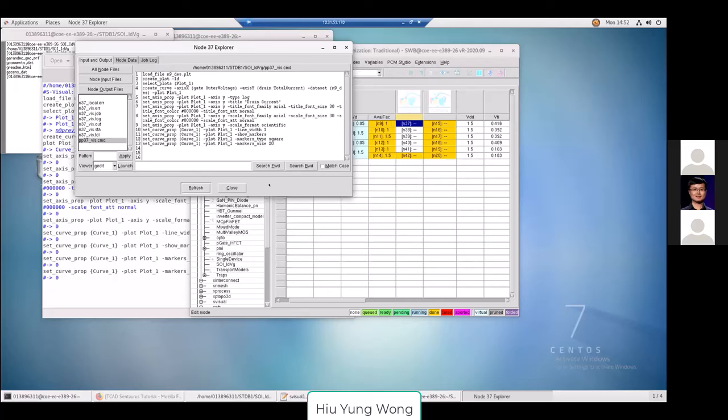Okay. And the file that we modified, that was the TCL file, right? Or SVisual? No, what we modify is the master file for SVisual. It's not TCL. It's a CMD. So you don't worry about the name. You just right click and then edit and then input command. Okay.